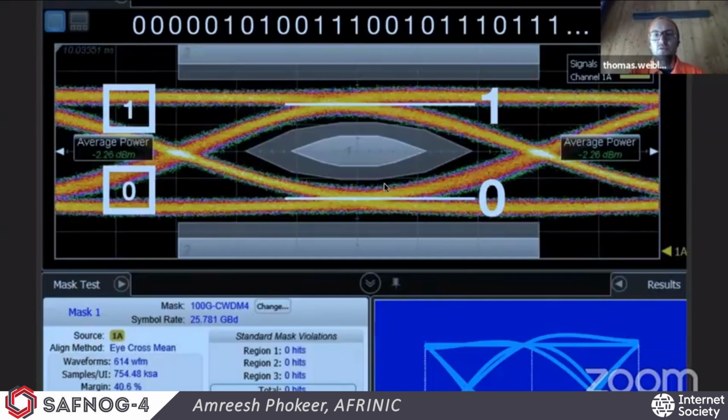We got those 2 events, 0 and 1, seen on the right side. And we really want to make sure that the high-speed signal doesn't cross that shape in the middle, because if it did, the receiver on the other side couldn't detect if it's a 0 or a 1. So we need a really defined status there, either down to the bottom to 0 or up to the 1 here. This shape makes the eye diagram actually an eye diagram. So we don't want to cross that eye.